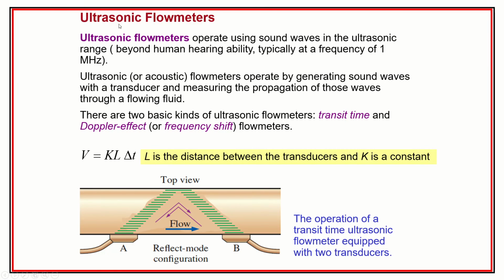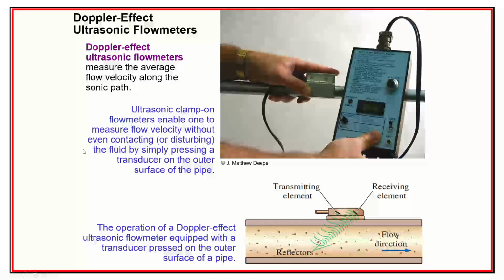There's also the ultrasonic flow meters. I used to have tons of literature on these. Back before the internet, we used to call up and ask people for their literature. The ultrasonic flow meters love to bounce waves off of stuff, and this one goes on the Doppler effect. There are other ones that rely on some kind of disturbance, like particles, and it really needs some amount of disturbance. If it's too slow and too clean, you can't actually measure the flow.